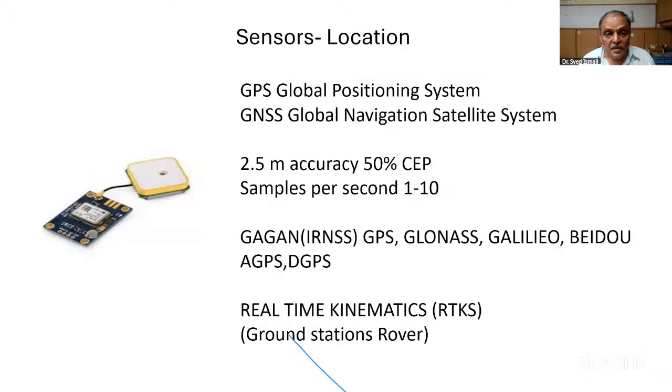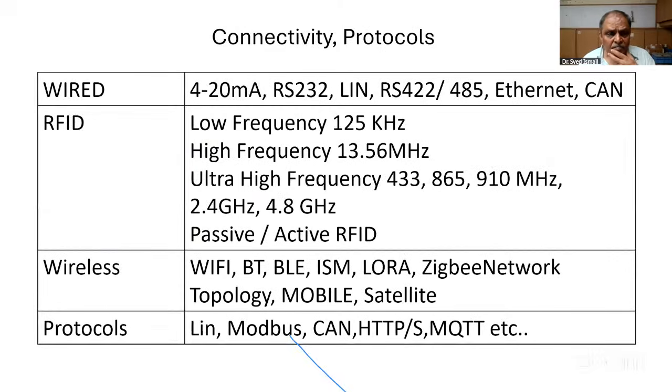Okay. GPS, all of you know, but very unfortunately, we don't have it in all the tractors or prime movers, because when that comes, it becomes expensive, and also we don't have a proper policy to support it. So we have satellites to measure the location. Now, what you use in cell phones has about 2.5 meters accuracy. But in agriculture, sub-meter accuracy, even up to 5 centimeters, is used, by RTKs. There are many guys in India also supplying. For example, laser leveling sensor is using the RTK. You must understand the principle for this when you want to go for it.